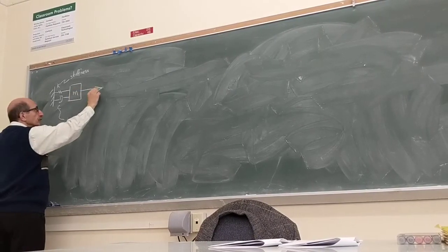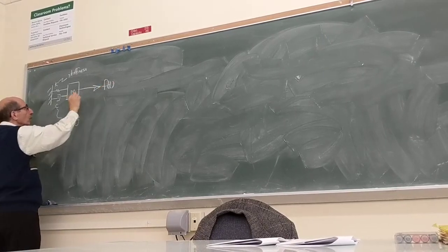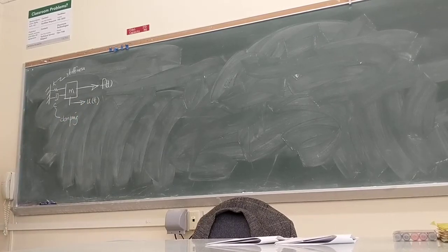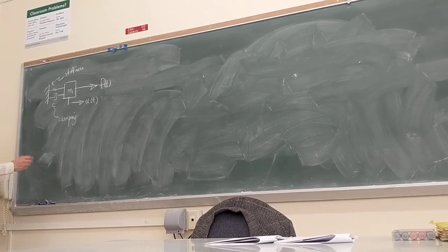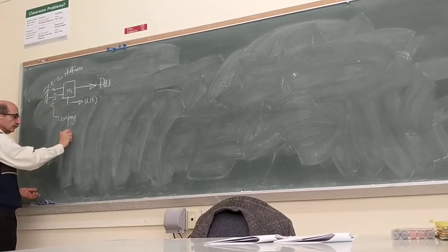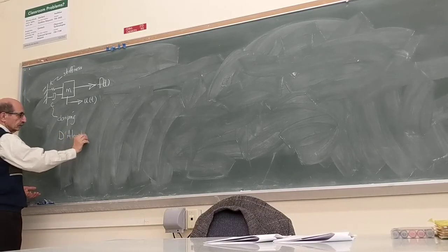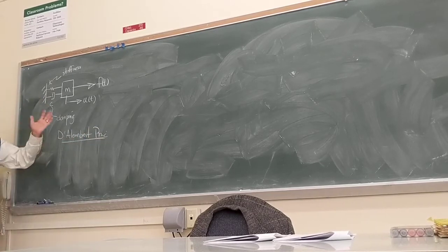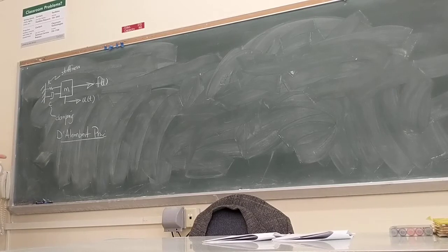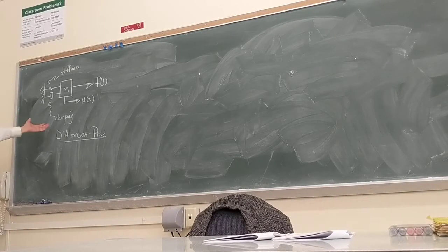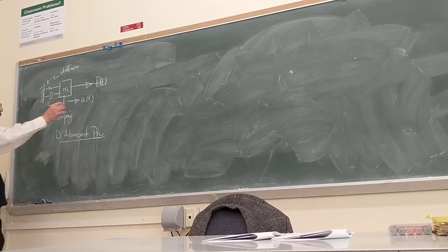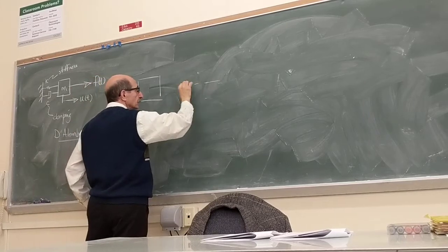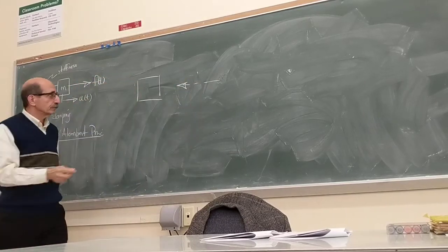Okay? So if this is subjected to an external force, it is going to move like this, and then we simply use the D'Alembert principle, which says you can basically set up the free body diagram of a dynamic system by including a fictitious force, which we call the inertial force, the force of inertia.